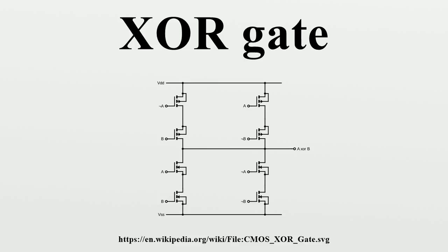In a CDMA receiver, correlators are used to extract the polarity of a specific PRN sequence out of a combined collection of PRN sequences. A correlator looking for 11010 in the data sequence 1110100101 would compare the incoming data bits against the target sequence at every possible offset while counting the number of matches.